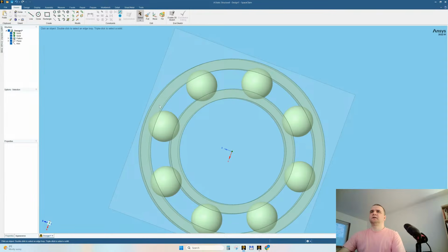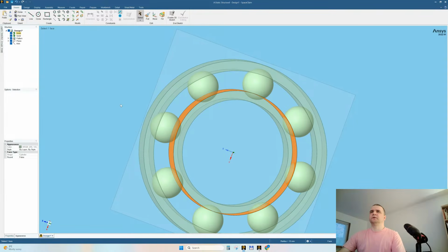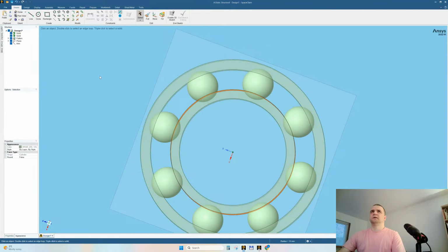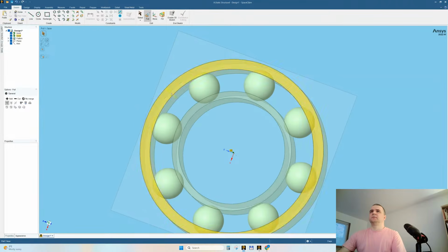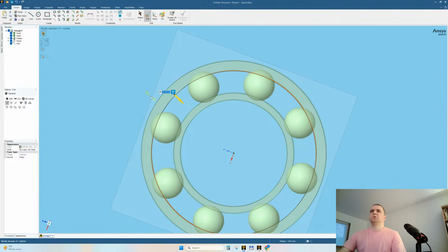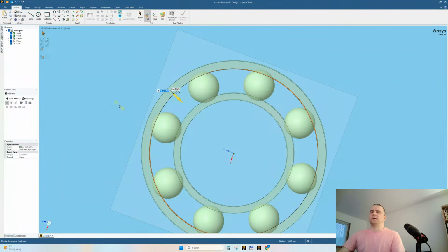I would like for the groove or interference to be, let's say, thinner. This means I will push this to be 13.5. All right. Enter, and this one, you'll understand why, because I need to give more space to the upcoming cage. There will be a cage and it needs to have space between these two races.